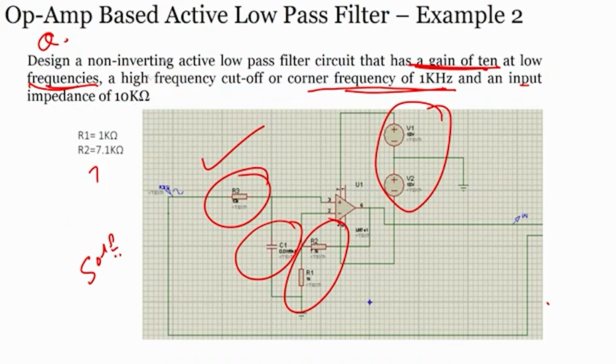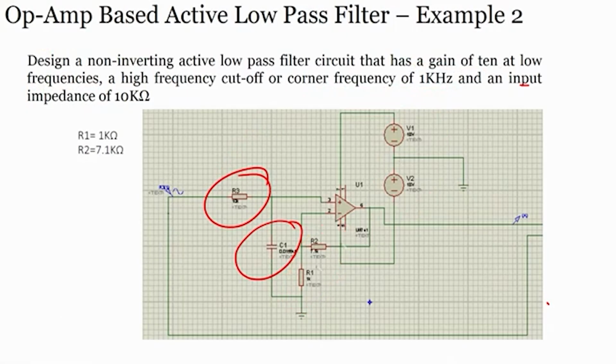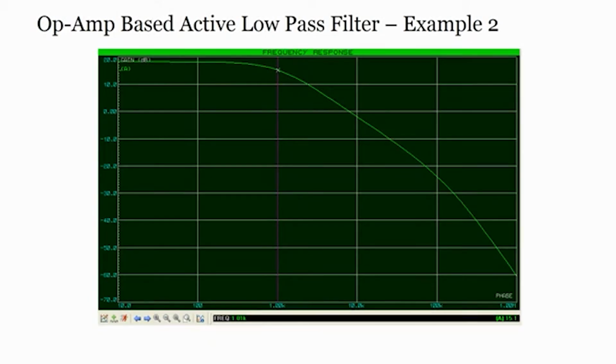So, let us come to the actual experiments and let us perform some experiments with low pass filters with passive and active components. When you actually perform this experiment and you see the signal, then you will find this particular slope, a fine slope here, and like I said, this will be your cutoff frequency somewhere next to here, and you can find this slope nearby the cutoff frequency. You can understand whether this is a single order or single pole active low pass filter. This is the amplitude and this is frequency. So, let us see